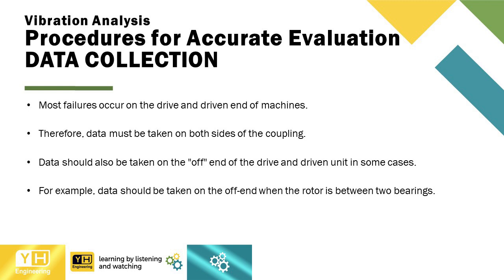Most failures occur on the drive and driven end of machines. Therefore, data must be taken on both sides of the coupling. Data should also be taken on the off end of the drive and driven unit in some cases. For example, data should be taken on the off end when the rotor is between two bearings.